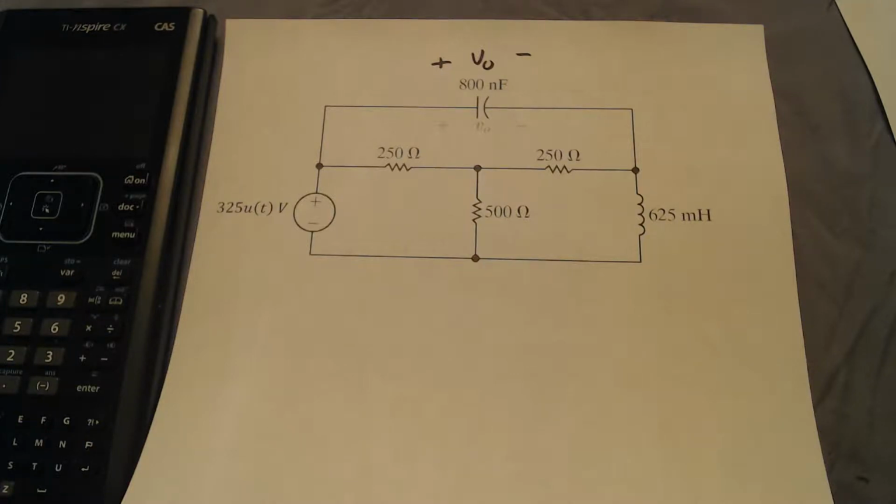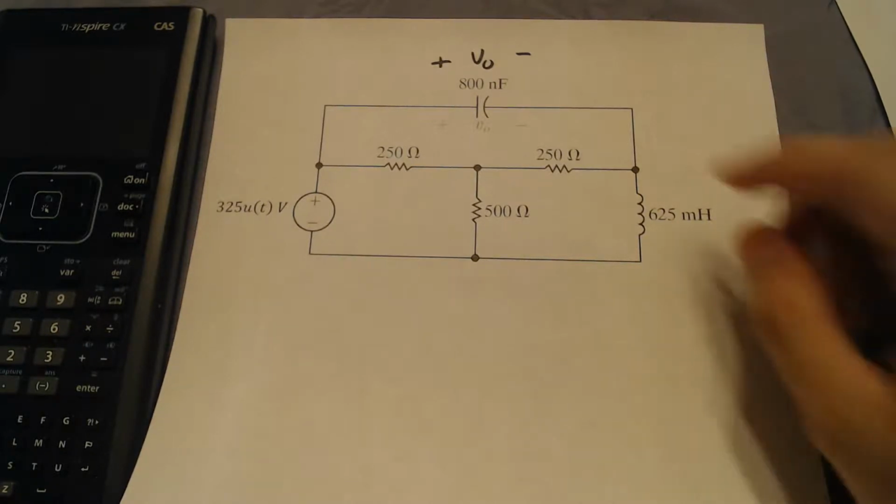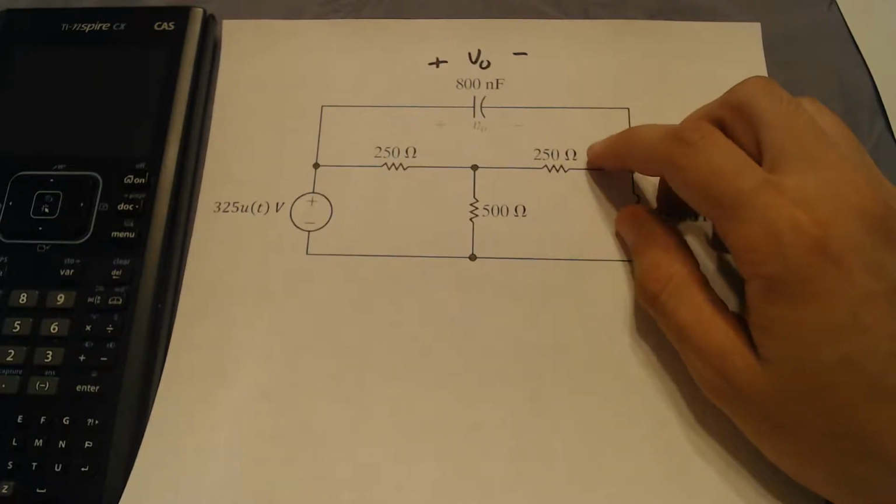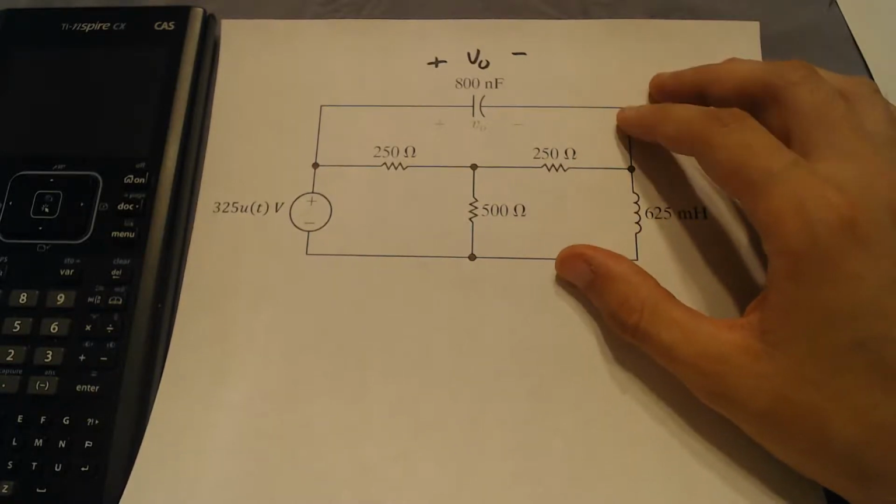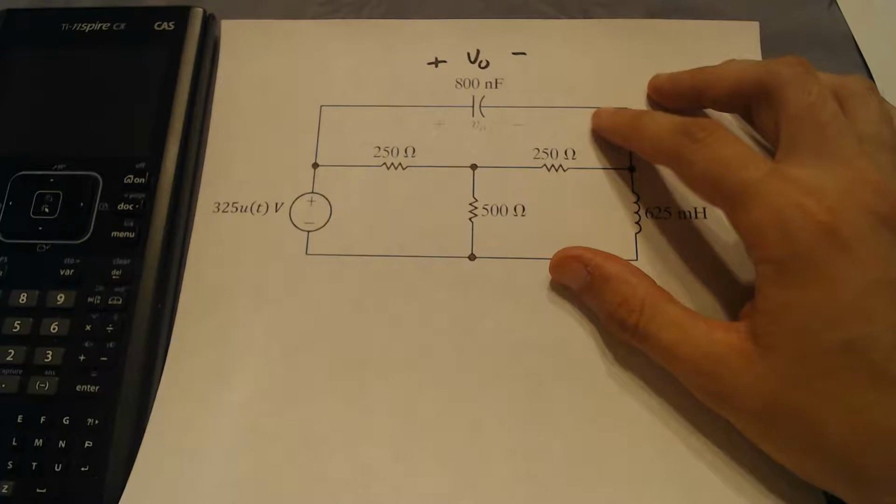In this video, I'm going to show you how to solve a circuit using Laplace Transform with the TI Nspire. In this circuit in front of us, we have to solve for V0, but for this circuit specifically, in order to solve for V0, we're going to have to take the Laplace Transform of this circuit and solve this circuit in the S domain, and then take the inverse Laplace of the relevant equation.